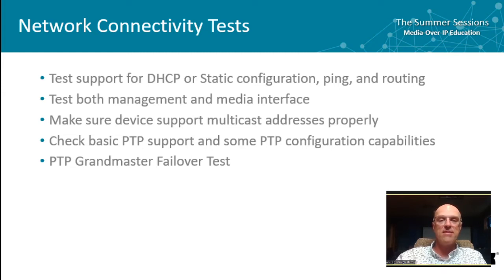Then there's some basic PTP tests, making sure that the device can actually lock to PTP for a given domain, that you can change the domain, that the device is not hard-coded to working only, let's say, to PTP domain 0, and that you can set it and it actually works properly.